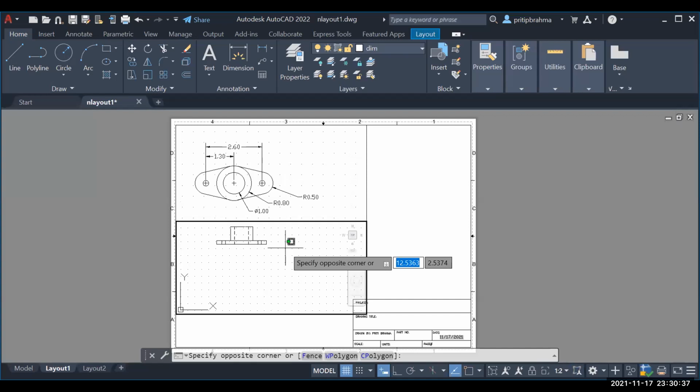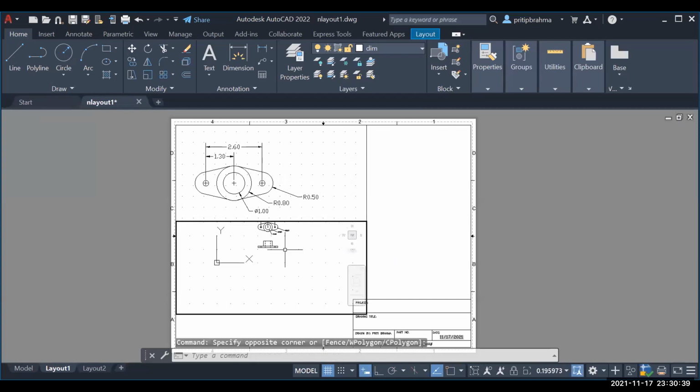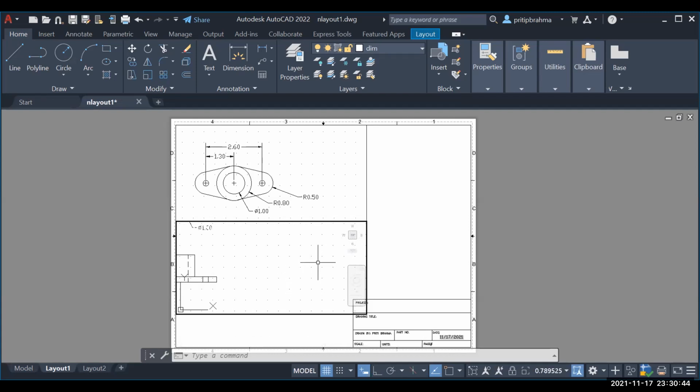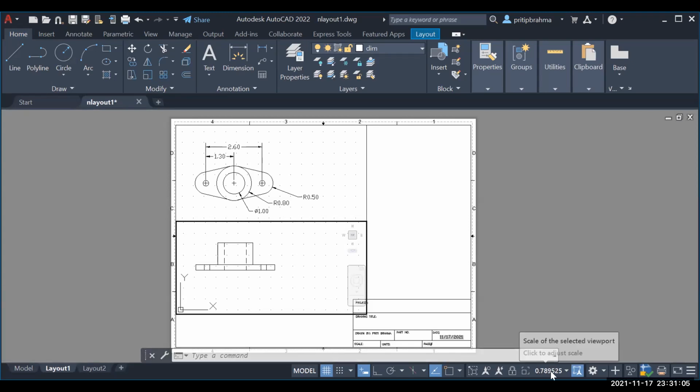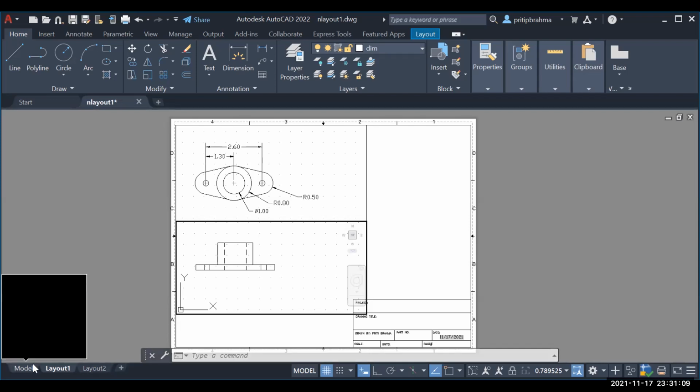I don't know if you noticed, but I double click in here, right? Look, the 2 objects are there. I zoom in. That doesn't change the scale. Yeah, it is changing the scale. This is what you have to pay attention to, is the scale. It's totally changing. That's why I pointed that out, is you have to pay attention to what your final scale is and put that scale in your title block. Multiplied by whatever. If you drew 1 to 1 in model, then your final scale is whatever is listed here. And if not, you need to reduce it by whatever you drew in model.